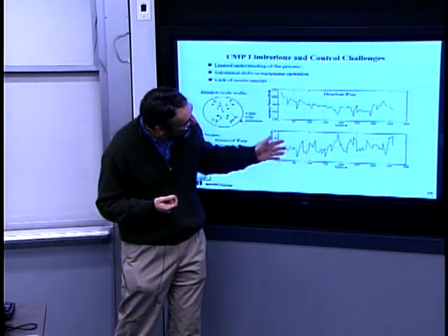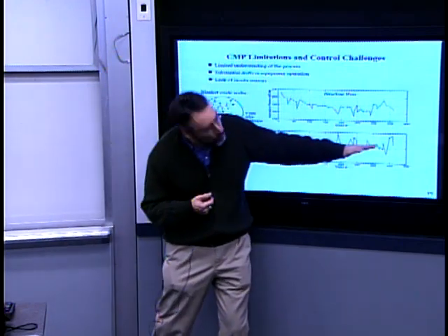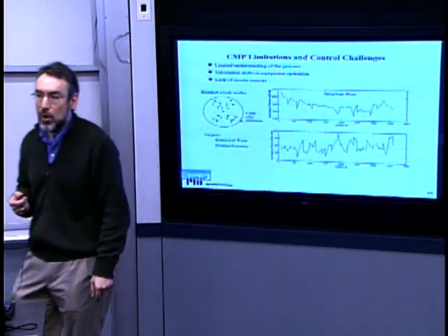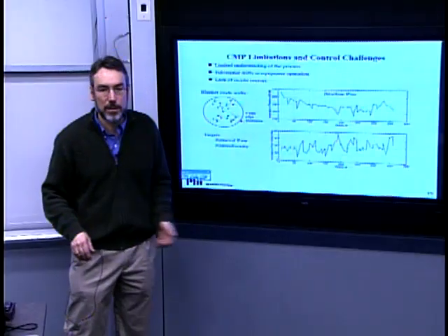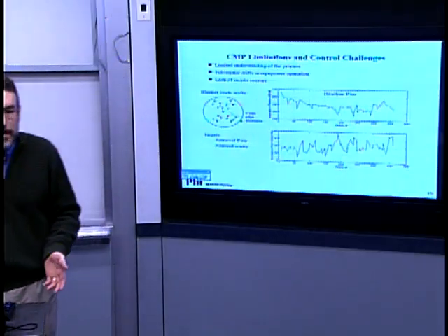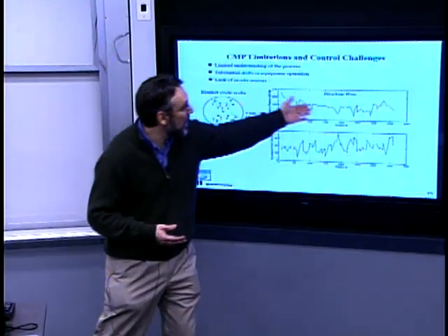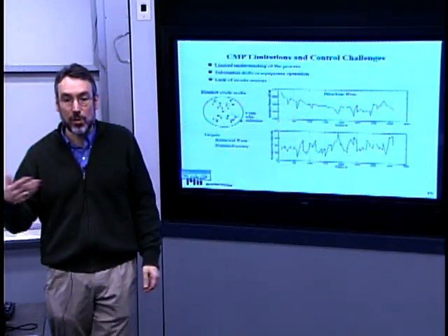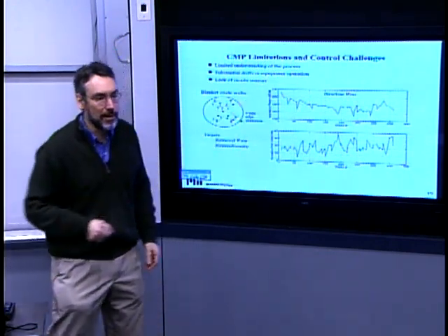one would find, maybe you can see it, looks like there's a slight increase in that non-uniformity over time. The pad is not quite as uniform as well. So this is the kind of temporal wafer-to-wafer variation that you don't want, and we would like to understand it. If there's a systematic trend, then maybe there are control approaches that can be used to compensate or correct for that. Yeah? This polishing seems to be a bad idea to me.